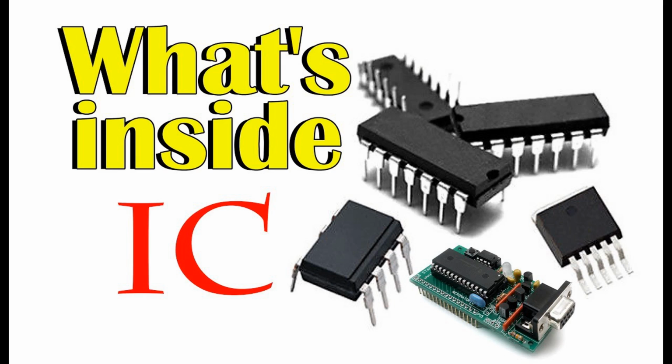Digital signal processors, DSPs, are specialized microprocessors designed to efficiently process and manipulate digital signals in real time. They are used in a wide range of applications where fast and efficient signal processing is required. Here are the key features and applications of DSPs. Key features of DSPs. Efficient signal processing. DSPs are optimized for mathematical and logical operations commonly found in digital signal processing, such as filtering, convolution, correlation, and complex arithmetic. Fixed point or floating point arithmetic.